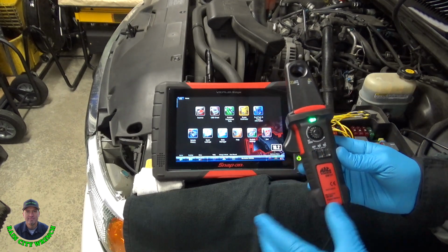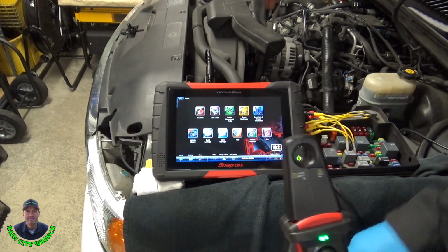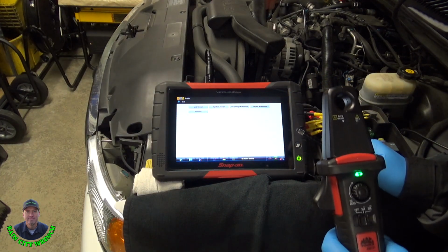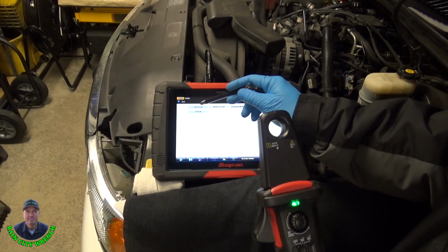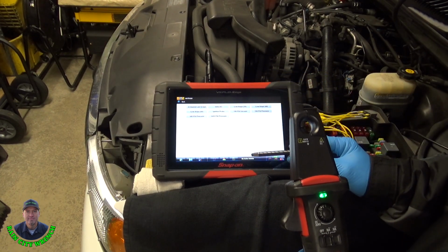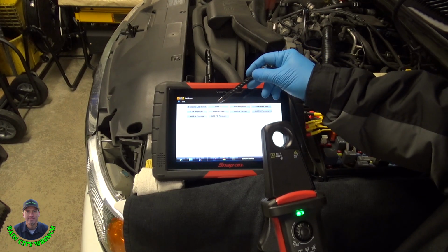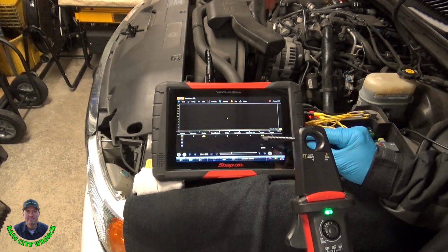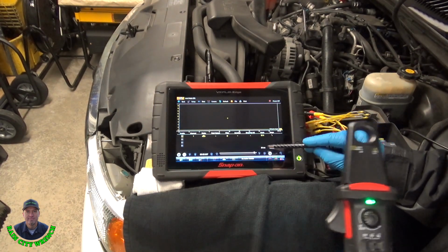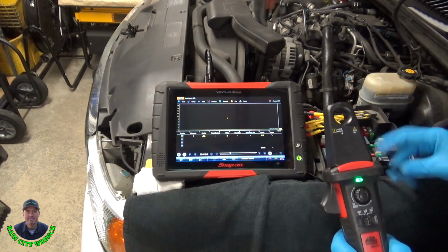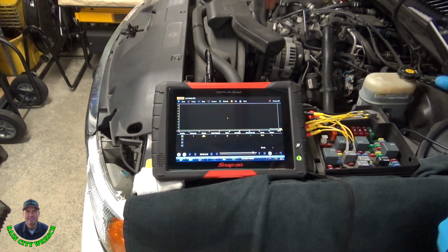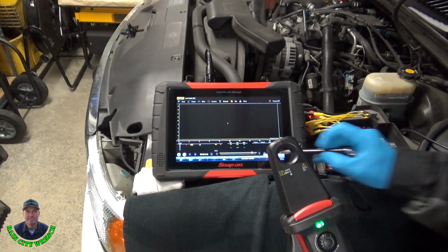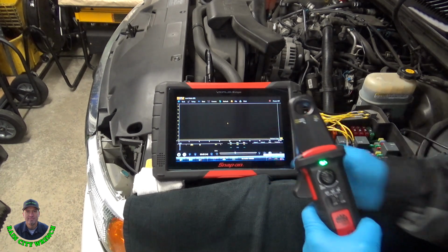We're going to turn this clamp on. We're going to go into scope multimeter again, and this we're going to do, we're going to go lab scope. We're looking at a quicker time event. We'll go low amps 20. So we're in 20, filters on, 20 milliseconds. Let's try that out. Let's actually make sure we're zeroed out. Yeah, we're pretty close.